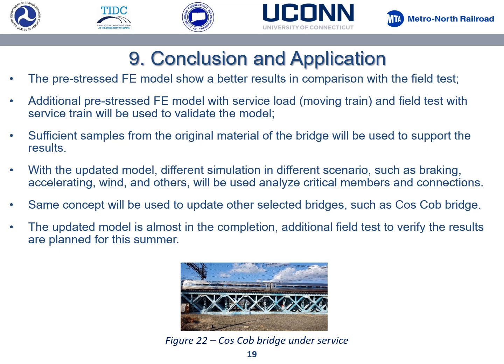With the updated model, simulations of different scenarios, such as braking, traction, wind and others, will be used to identify and analyze the critical members and connections. The same concept will be used to update other selected bridges, such as the Costco Bridge on figure 22. And we are hoping that with what we learned from the Devon Bridge, we can reduce the time to calibrate future bridges.